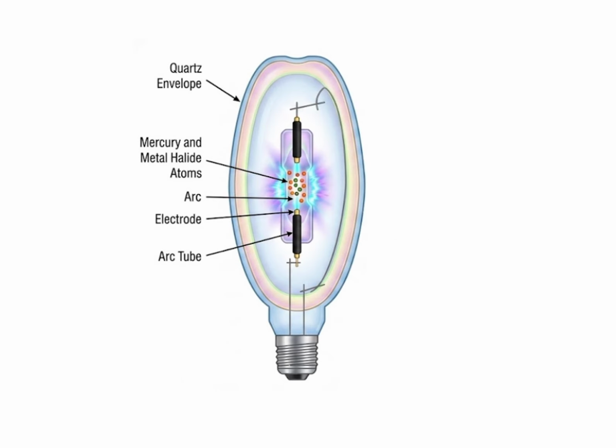So we will move on to the next lamp. This is called the HID lamp. It is a gas discharge lamp that produces light by creating an electric arc between two tungsten electrodes enclosed inside a quartz arc tube. This is the arc tube you can see. From this arc tube, two tungsten electrodes are connected, and between these electrodes the arc will be created. Okay, this is enclosed in a quartz arc tube, right?